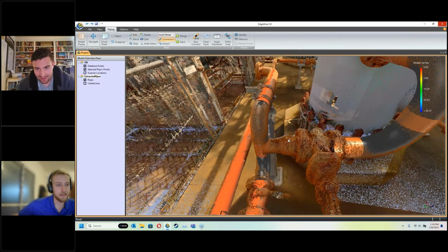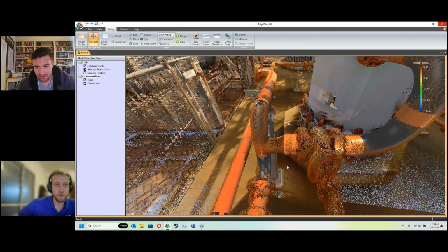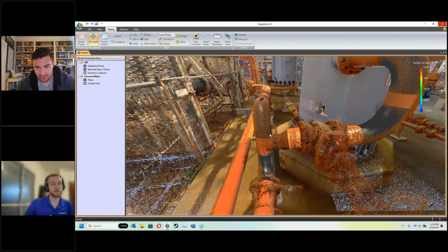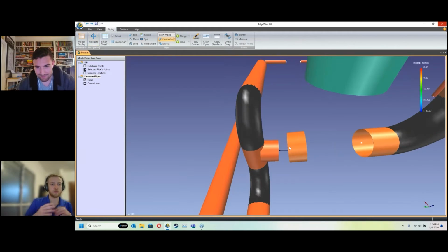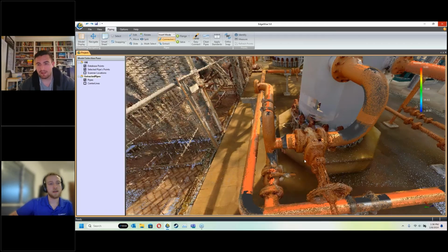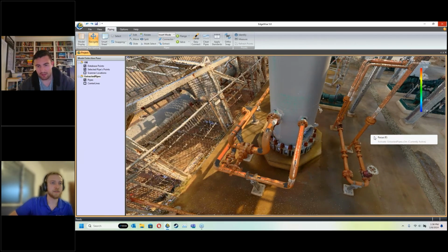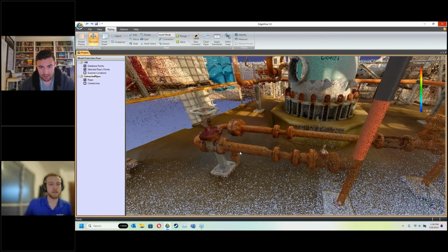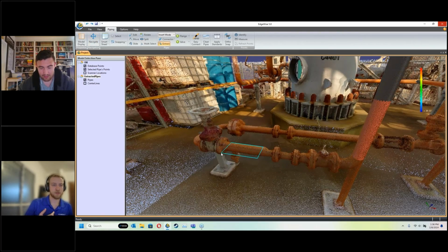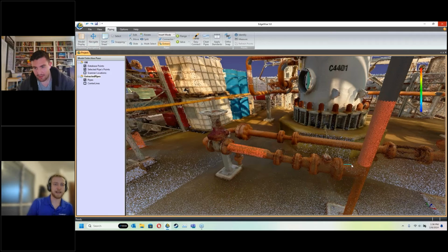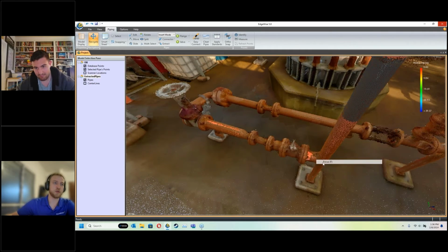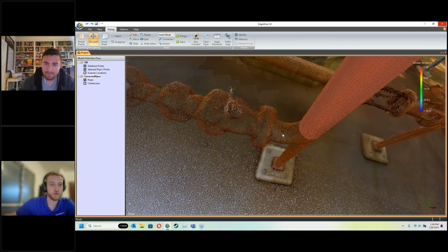Black elements are the straight sections that are temporary objects, representing segments of piping. As Trevor goes through the workflow, we will convert those into a single run of piping, a chain. The other curved elements are elbows. We don't have a visual distinction for the segments, but they are temporary. Tees, elbows, reducers, valves, flanges, those are going to be black elements. Those will stick around. But those straight sections are an intermediate connection to put everything together when we do spools.